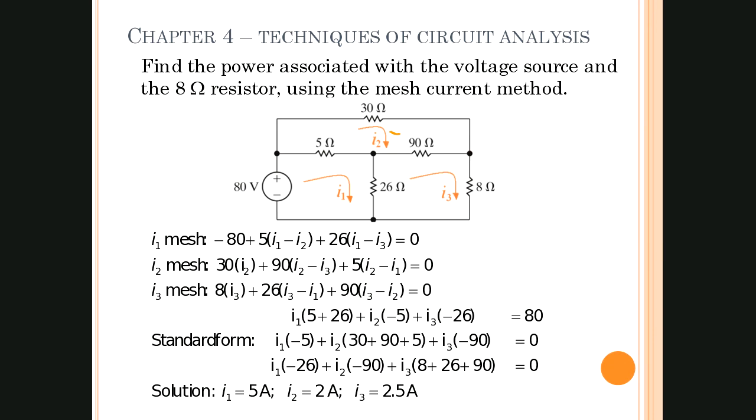We have the voltage drop at the 30 ohms. And again, by convention, let's go ahead and set up our sign notation. Since we're going clockwise, it's from plus to minus here. And then right here, that's minus, plus. I'm going to do the same thing over here.